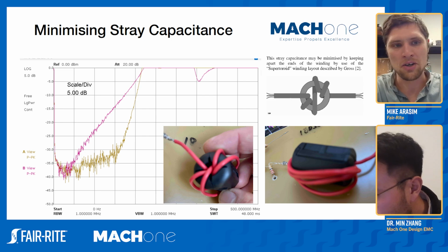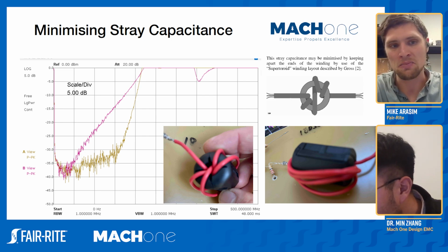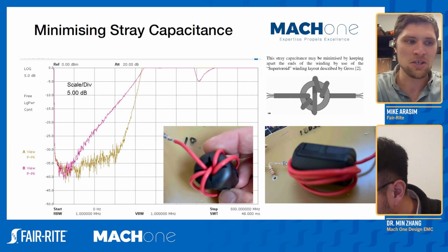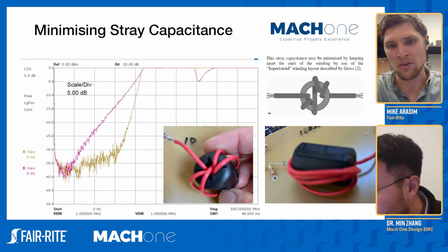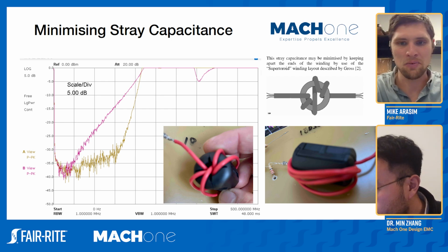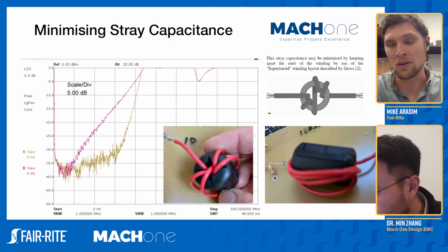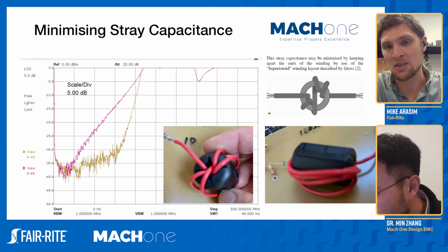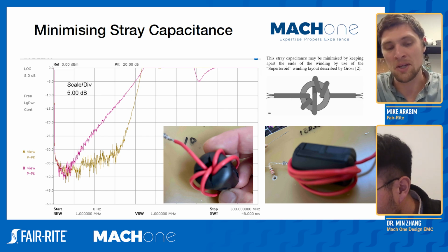You wind up getting parasitics, basically, and you're going to be decreasing the effective bandwidth of the ferrite. So you're going to wind up with, at the very, very low end of the frequency range where we'd maybe rate that ferrite, take 31 material, for example. If we're looking at 1 megahertz, you're going to be getting significant increases in impedance with each turn that you put on that core.